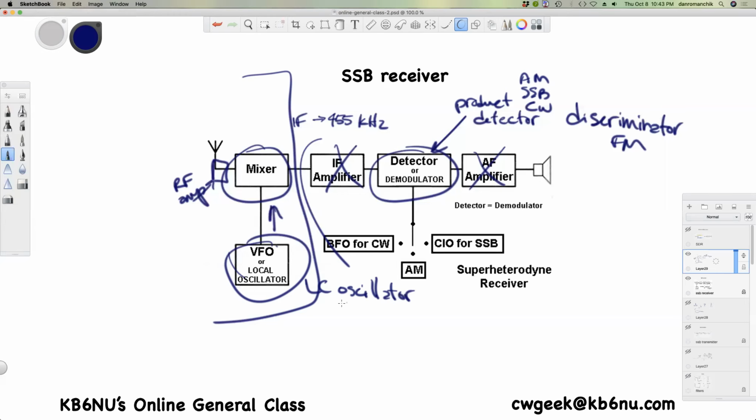Well, those things were prone to failure, and I say that seriously. As you know, these things had tubes, and as the radio heated up inside, the L and C values would change, which means the oscillator would change, and the frequency would drift as the radio heated up.